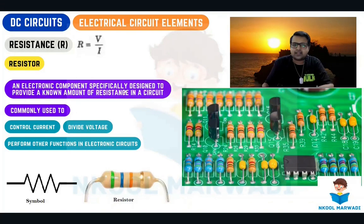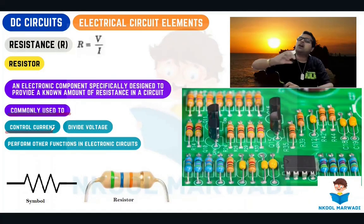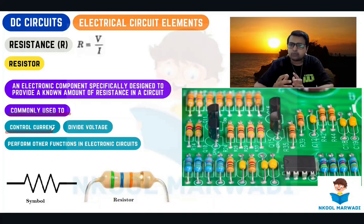Basically, resistors are commonly used to control current. Let us suppose we have some sensitive components in a circuit, and we want very little current to flow through those sensitive elements. There I can introduce high resistance, because of which a very low current will flow. So with the help of resistors, I can control the flow of current inside a circuit. It's so interesting, I can also divide the voltage, and this division of voltage is very important.